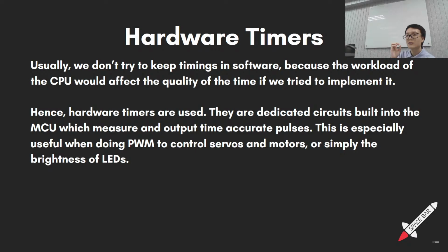So the amount of time it is on versus the total amount of time. This goes on forever, and this is essentially a PWM signal. What matters in PWM is the time on versus the total time, which we usually call T. By the way, this is the time axis, and this is your voltage.